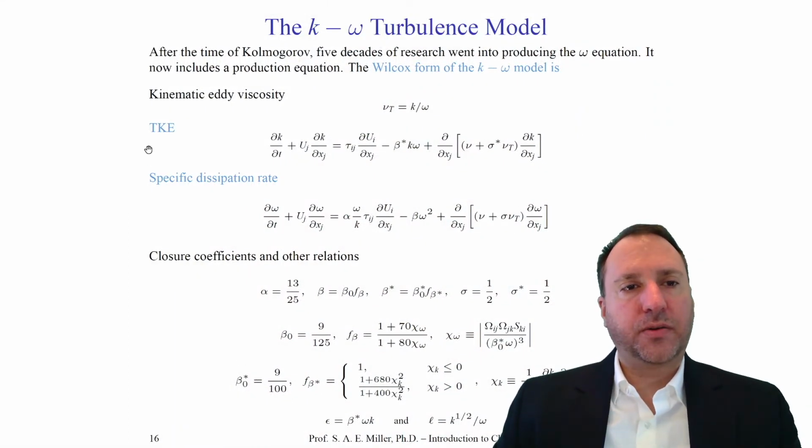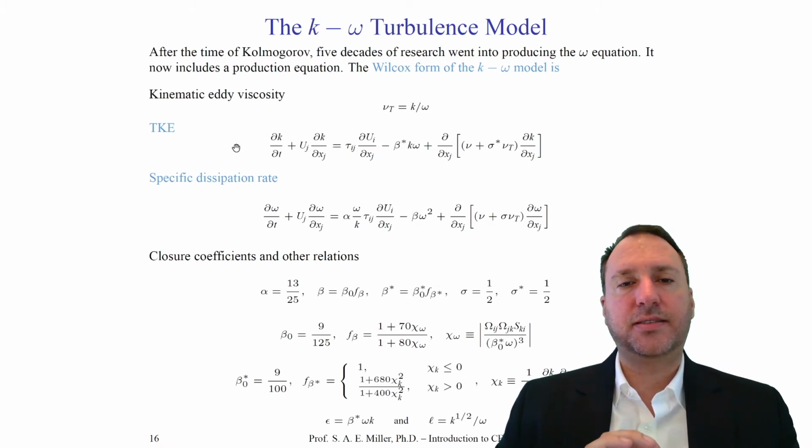As before, we had an equation for turbulent kinetic energy. This is essentially exactly the same trace of the Reynolds stress equation, and we get an equation for turbulent kinetic energy K. This is one particular PDE that's being solved in the two-equation solvers. Remember, two-equation models and closures have two equations. Of course, the second equation will be omega. This is the equation for omega.